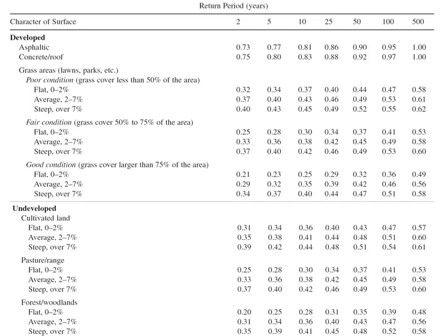Of course, the other is that concrete or asphalt has a higher C value than grass. Now that's probably so obvious that we don't even need to discuss it, but I will anyway. Grass is going to allow for more infiltration because there's a more direct pathway between the atmosphere and the soil. If you've got 3 inches of concrete between the atmosphere and the soil, then the water can't get through quite as easily. It's got to find cracks in the pavement in order to infiltrate even just a tiny fraction through. Okay, so that's an obvious thing.